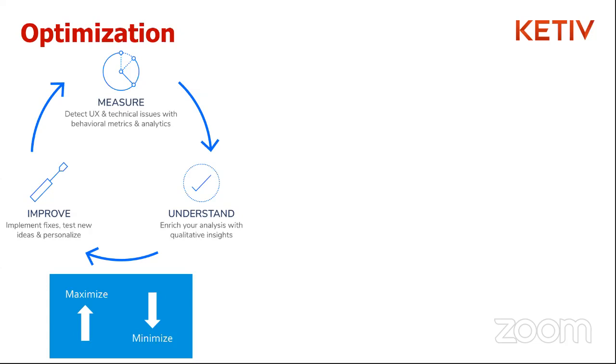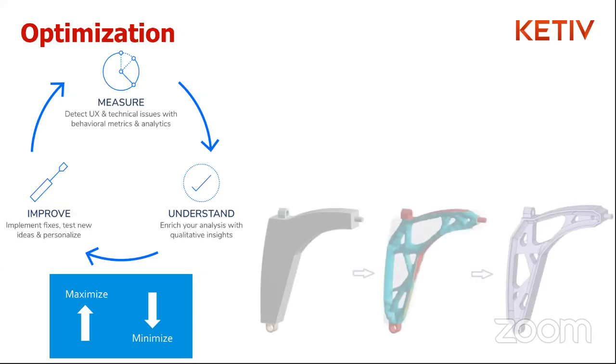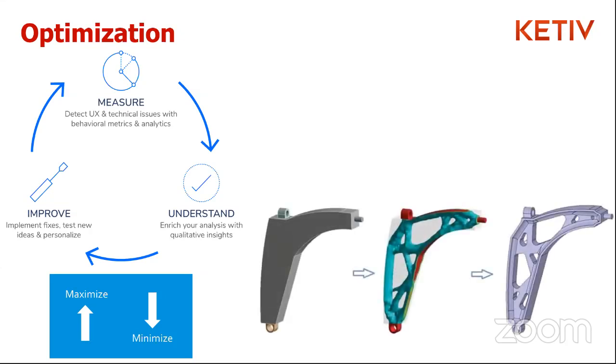Yep, absolutely. You might have heard the term shape optimization, topology optimization, geometry optimization. They all pretty much mean the same thing. Essentially, it comes down to taking your CAD geometry and making it, well, better in one way or another, whether that means making it lighter, whether it means stronger, whether it means a combination of the two.